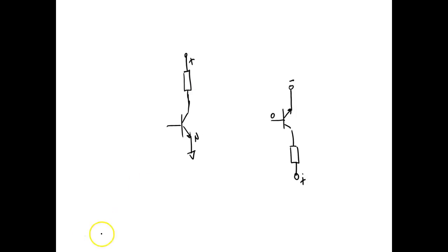So what I'm doing over there is I'm controlling the direction of the DC motor by changing the polarity of the current. The other method that we would see, that y'all would do in motor controllers, if y'all remember the reversing controllers in motor controls, what we did is we controlled it in an H control, what a lot of people call an H controller. This is pretty standard to control it with relays.